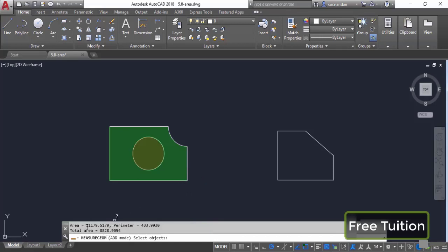So the total area was this, and the area of the circle has been removed from that, and the remaining area is 8828.9054 unit, which is the area of this green portion excluding the area of this circle. Now press enter. So in this way you can find area of different geometries using the area command or the area inquiry tool of AutoCAD.